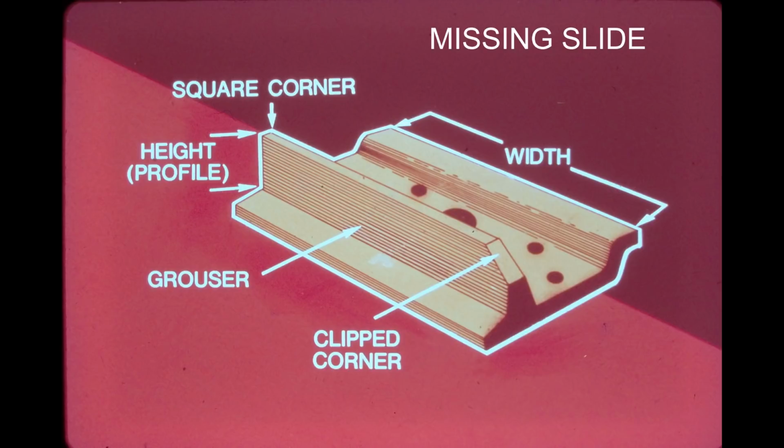Shoe width also should be tailored to the application. Wide shoes provide flotation and are used in soft soil, such as sand or marshy areas. Generally speaking, the proper shoe width is dependent on tractor weight and soil conditions. But remember that the narrowest shoe that provides flotation is the shoe that should be used. The narrower the shoe, the greater is the pressure per square inch on the grouser. This pressure results in good penetration and good traction. Using shoes that are too wide can result in the grouser not penetrating and in increased wear on undercarriage components.